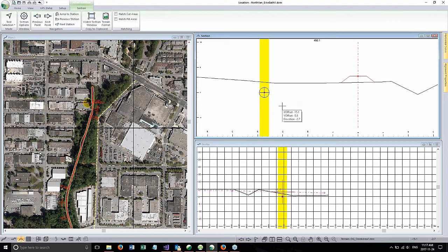And let's see, there you can see what this GPS is reporting as my vertical position. And because it's a location service, I don't even think it has a vertical position. It's completely meaningless. It's just set at 0. Real mapping grade, the GPS will return a better elevation, and you can use it for what it's worth. Be careful with it. Also, you have to understand that the map data that you're working with needs to be in the same datum as the GPS datum. So there may be some vertical differences between the two vertical datums. So all this stuff you've got to worry about.